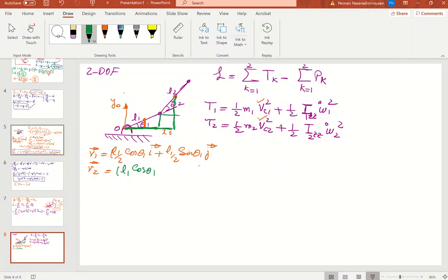It's very clear. Look at here, guys. How much is the angle? This is theta 1, yes or no? This is trigonometry. So this value is plus L2 over 2, half of that, in cosine of what? Theta 1 plus theta 2. Right? This is simple trigonometry. So the mass center of link 2 with respect to the frame coordinate system is this.